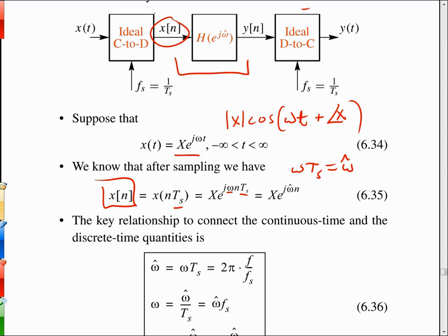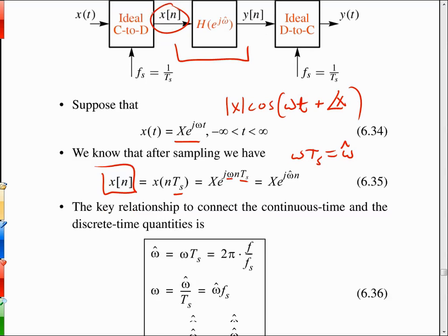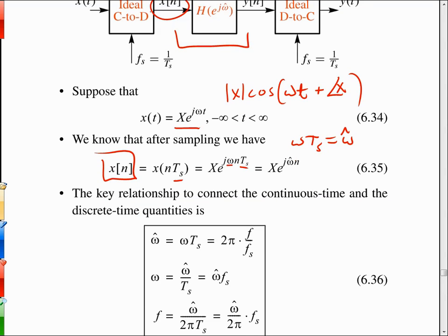And of course, when we do this sampling operation, we've learned already that what do we want to make sure we obey to avoid misunderstandings later? We have to sample according to the low-pass sampling theorem, which says we have to make sure that our sampling rate is at least greater than twice that maximum input frequency. Otherwise, we have aliasing. But assuming we don't have aliasing for the moment, that sequence that comes out, this guy right here, is now in the discrete time domain.